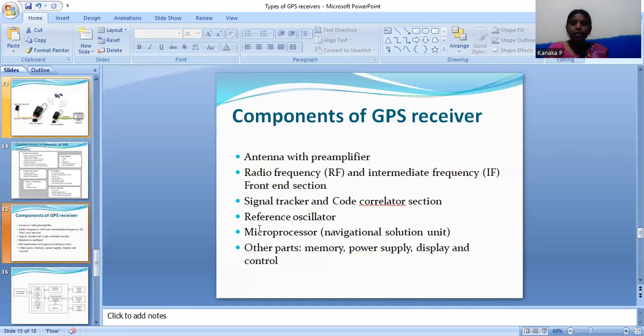In the phase difference method, the speed of light in vacuum is known, but the measurements are not taken in a vacuum, so corrections for atmospheric conditions have to be made. Further, because of the great speed, direct measurement of the time taken to travel is not possible. So the EDM instrument measures the phase difference between transmitted and received signals.